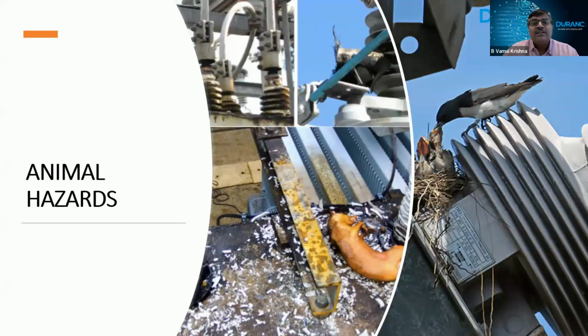One more aspect is animal hazards, which are well known. Typically, mice, rats, birds, dogs, cattle, etc. pose threats to substation operations. In fact, it was noted in one of the studies that birds cause up to 25% of the power outages at utility substations, from nesting to arc flashes to fire hazards. Nesting birds attract predators, typically raccoons, cats, and snakes, which often cause outages because they climb through the station looking for these bird nests. The accumulation of bird droppings can be corrosive to materials and equipment, causing damage.